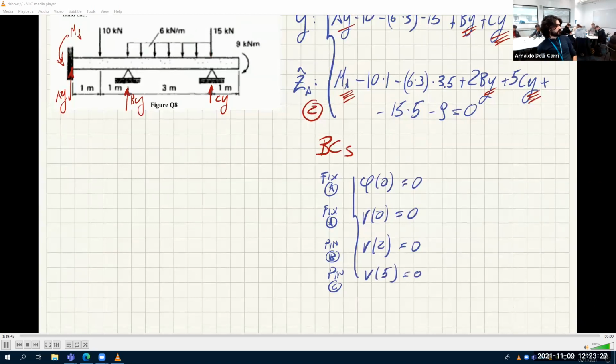You look puzzled. Why don't the supports at the bottom get unknown? Why do they only constrain it in deflection and not in angle? Because a pin does allow for slope. Because the beam can rotate around this.